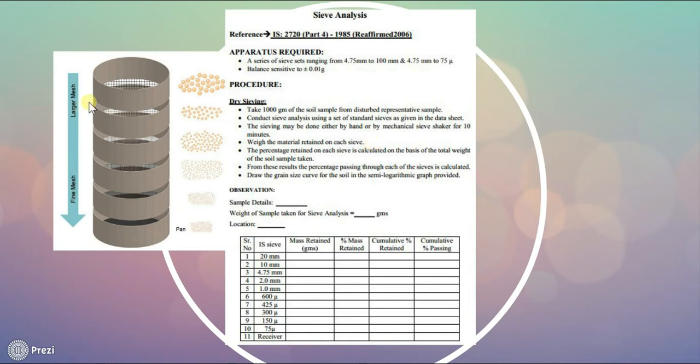This works as per shown in figure. Coarse soil particles are retained on larger meshes and finer soil particles are retained on finer meshes. Therefore, after 10 minutes, all sizes of soil particles will be settled. Then weigh the material retained on each sieve.